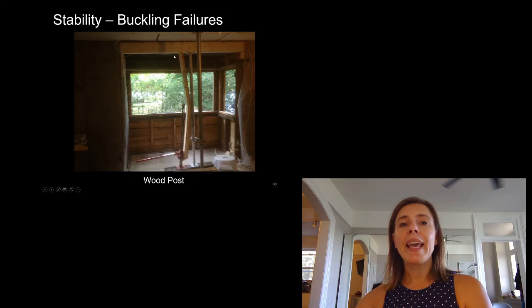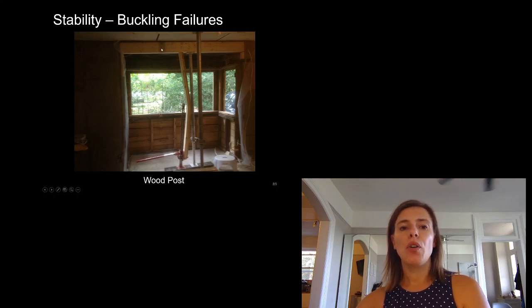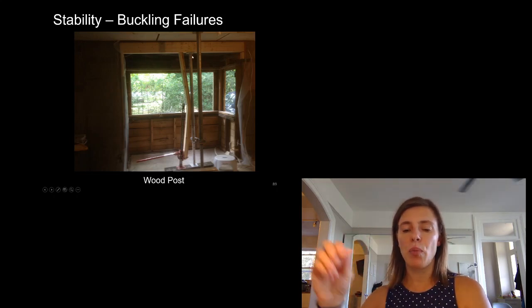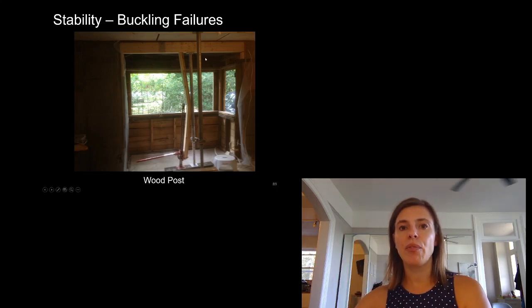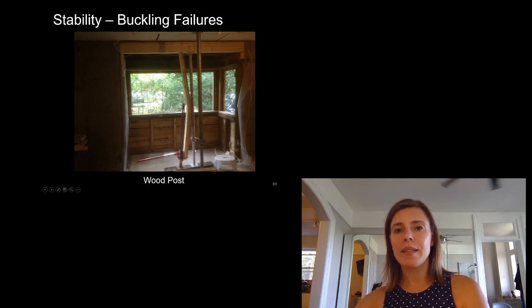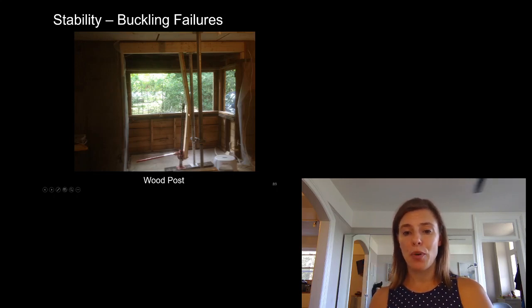When we were jacking our ceiling to put our new beam in, we used a steel post jack, but that doesn't have small scale movements. It only has large scale, several inches movements. So what we needed to do was jack it in increments and then put new pegs in as we raised this. When we got to the height we needed, we realized we were really close to buckling two 2x4s screwed together.